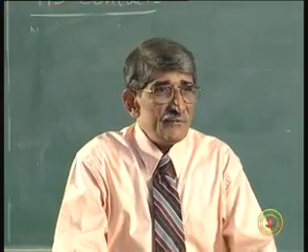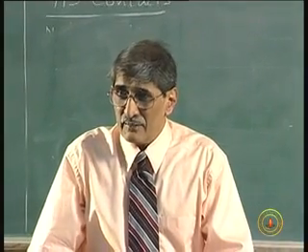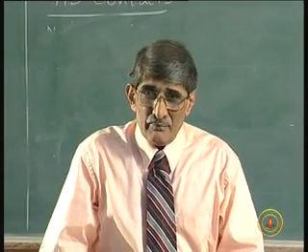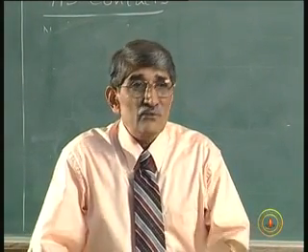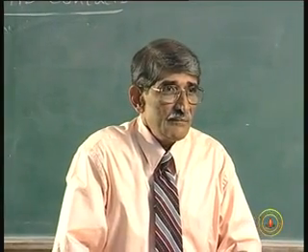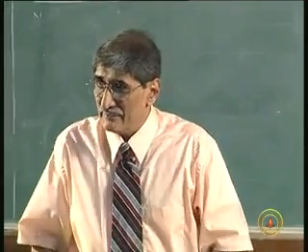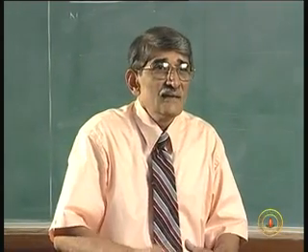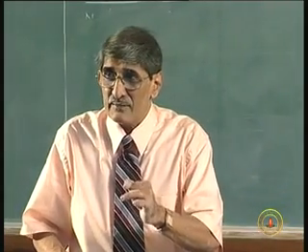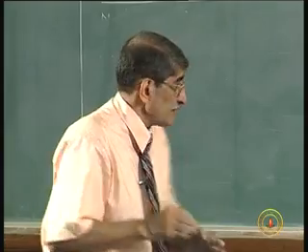Phi m less than phi of s in n type substrate, metal semiconductor contact becomes ohmic. But an in-between situation can also become ohmic, because so long as the difference is small, it can be ohmic. If the difference is large, it is rectifying. That is the point that I am trying to stress, because that is missed out in many places.